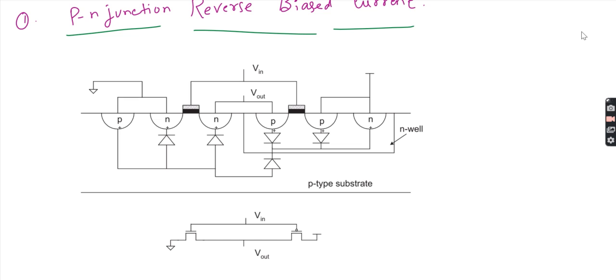You can see this is the physical structure of CMOS inverter. You can see here, this is the schematic we showed, right? See here, this is schematic. So let us identify the terminals. This will be your PMOS, this is your NMOS. So simply, I can say this is VDD. Then this terminal is nothing but source terminal. This is the drain terminal. Then this is the drain terminal. This is source terminal. This will be your VSS, Vin, Vout.